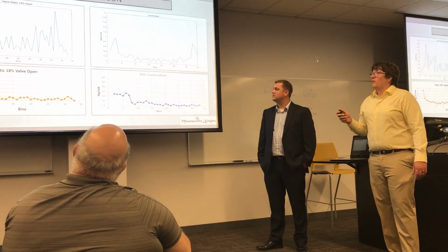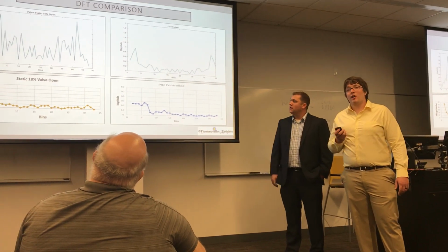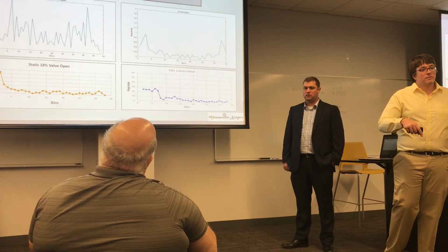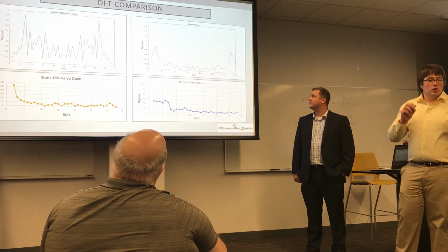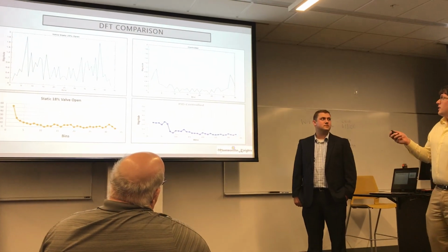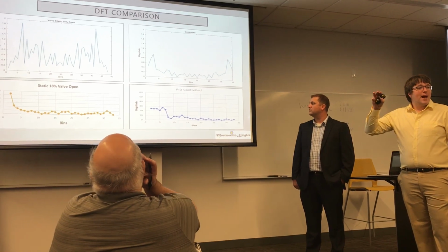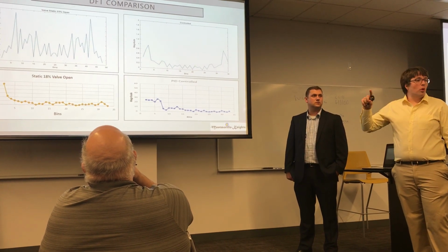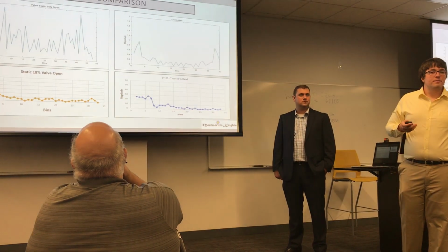What you're going to see is for both cases, we were able to reduce the magnitude of these frequencies, especially the higher frequency ones. Why is that important? Lower frequency, lower magnitude means lower energy, right? So we're able to say with the data to back it up that we are controlling slug flow positively, the way we wanted to do it. One thing I do want to point out with the PID controlled for the pilot scale, bottom right, is a little bit higher magnitude on the lower frequencies. We included the overshooting portions of it, which would contribute to a higher magnitude in your lower frequency zones.